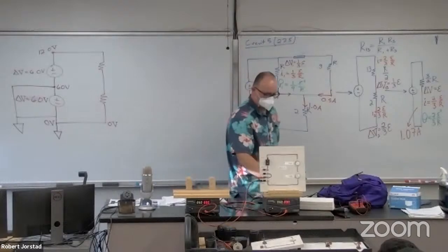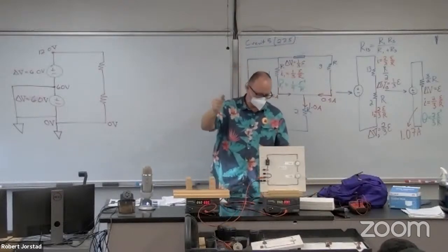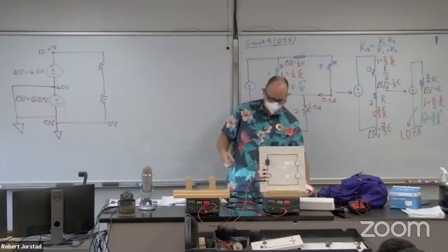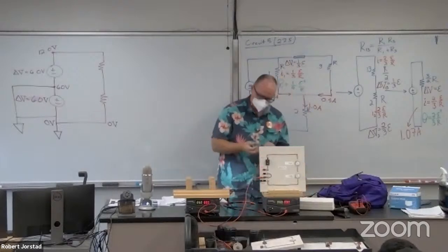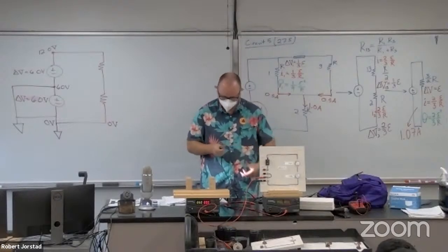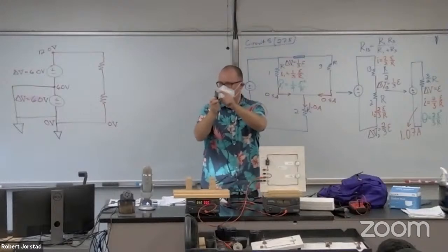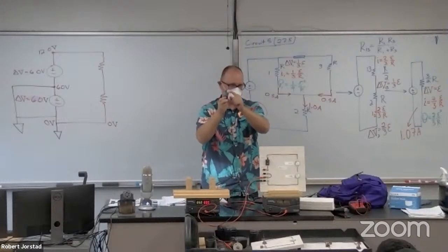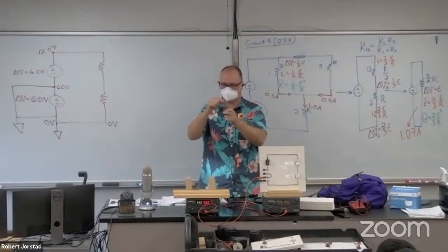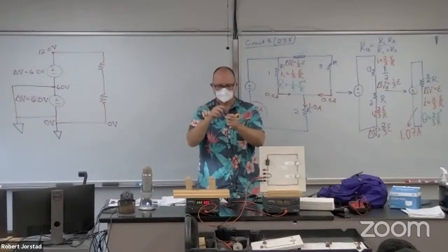So that's why I'm going to take one of these. Now these, you've probably seen these before. It's those little gray plugs. Which one is which? This one? Okay. The idea here is this metal tab is designed to be screwed into the wall so that this is actually grounded. So if you've ever seen outlets that don't have the 3rd prong, this is getting more and more rare, which is a good thing.